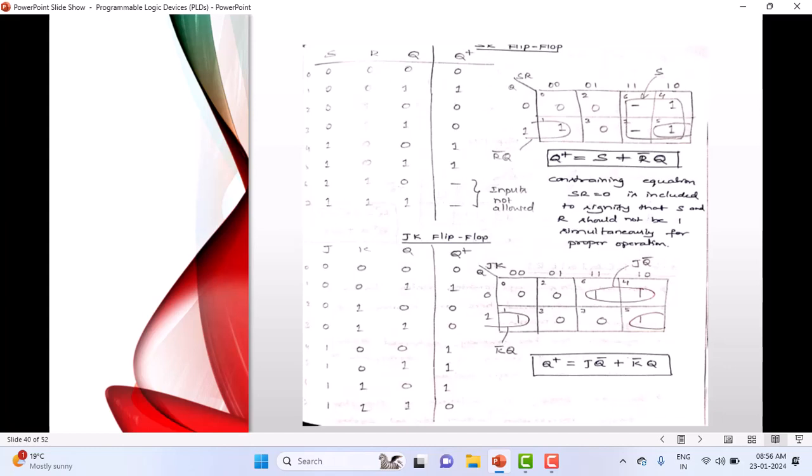First write for the D flip-flop, then we can go for the T flip-flop. First write the truth table of the D flip-flop, then you can write the state table for the D flip-flop. Write the truth table for the D flip-flop. You have only 2 rows, right? But you have to make it 4 rows here. Why 4? In the state table, you have to know that along with D there will be Q also, right?